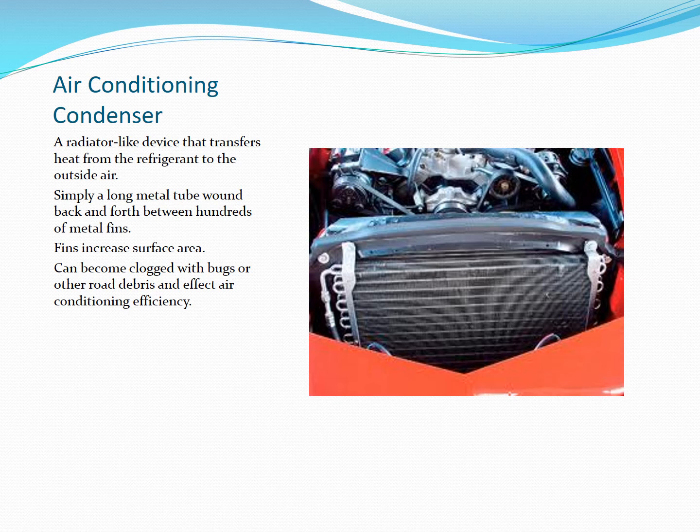One of the things we look at as a technician is to see if that condenser is blocked. Does it have a bunch of bugs in it? Is it clogged with leaves or dirt or any other debris? Vehicles that are run on the highways or run at night, most of their mileage might have lots of bugs that have folded over the fins, and that is going to cause the air conditioning system to be less efficient. In other words, it's not going to cool as well. If airflow is blocked over that condenser, the air conditioning system will not cool as well as it should.